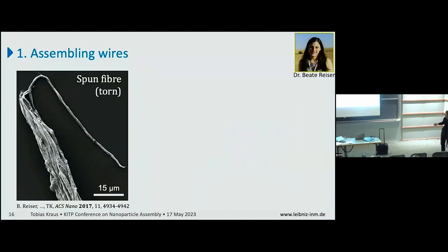And you will see that if you look now at the damaged images. So this is one electron micrograph of a fiber. You see that here, which was ripped apart. And when we first looked at it, it reminded us of failure in either ropes, in hemp rope, for example, which often looks like this. You very often rip out one or some strands, but also tendons, actually. I hope nobody has ever seen that, but if you rip apart a tendon, then also you often rip out strands. And the reason for that is, of course, that these are all hierarchical in structure.